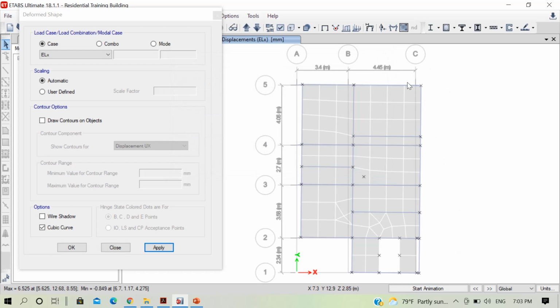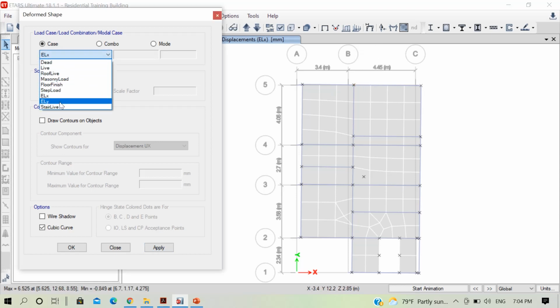So you just make note of all these deflections. Our larger deflection will, in this case, be delta max. Our lesser deflection will be delta min, and then try to find the relationship between delta max and delta min. Similarly, for the same story 1, I will check for earthquake load in y direction and I will apply it.